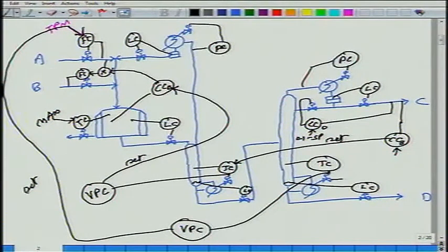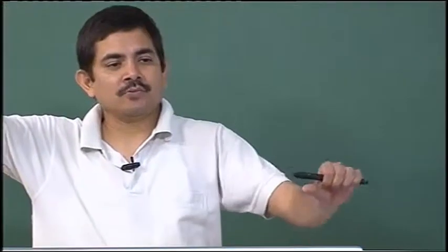I look at the boil up. If it is not at maximum, I jack up the throughput a little more. That's what an operator would do, right? Boil up is not at maximum, I can process more A, keep jacking it up.